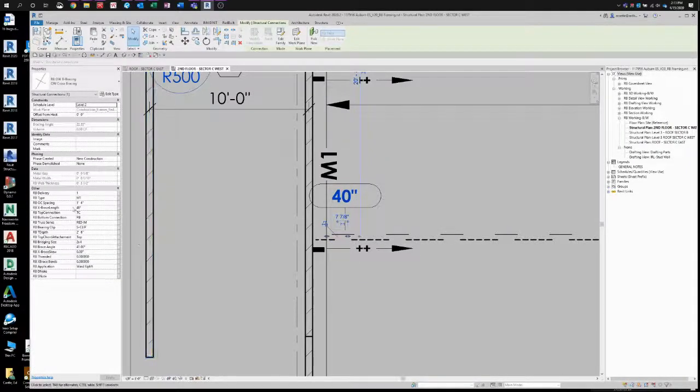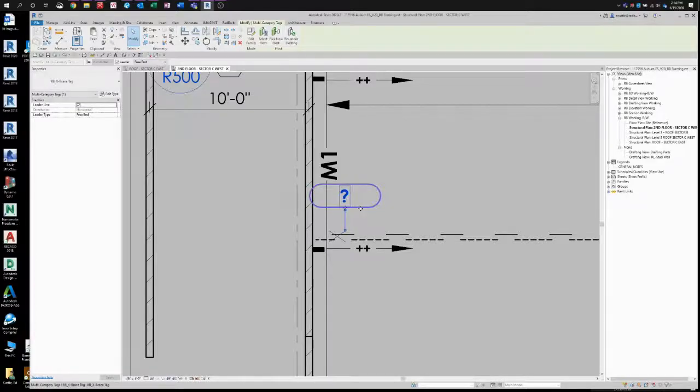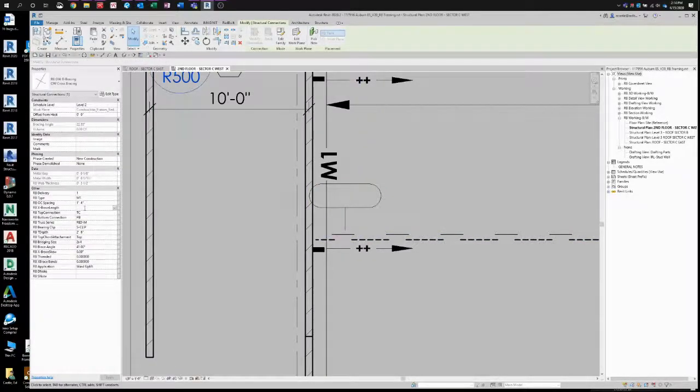On the cross bracing tag, what shows up is the length that you've set for your object. So your cross bracing here under express brace length, you need to have that filled in with the inches of the brace length, and it'll fill out. If you do not, you'll get a blank with a question mark. Always make sure that your cross bracing has been set with the inches so it shows up.